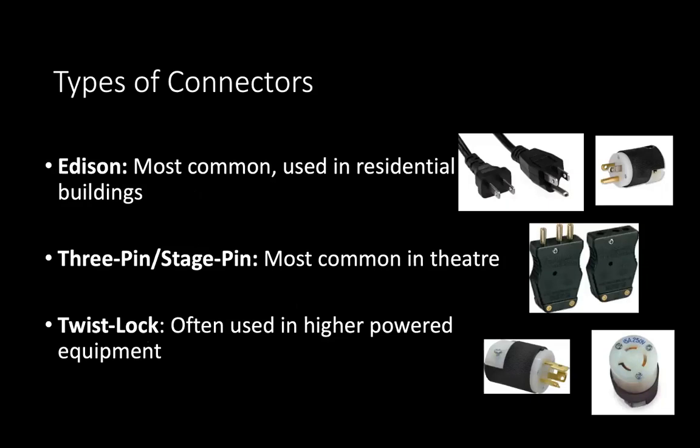But beneath that is our most common you'll see in theater, which we call a 3-pin or a stage pin. And we use them because they're so bulky, and when you're up at the catwalks working, it's pretty easy to drop cables and stuff like that. So we use pretty beefy connectors in order to not bust them constantly. Edison connectors are really useful in household use, but we're chucking these cables everywhere and abusing them. So we need a little chunkier connector, and that's why we use the stage pin.